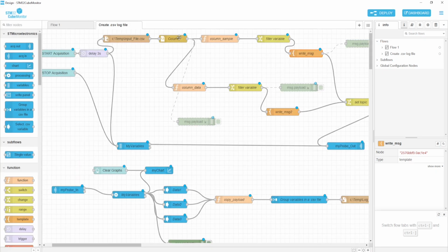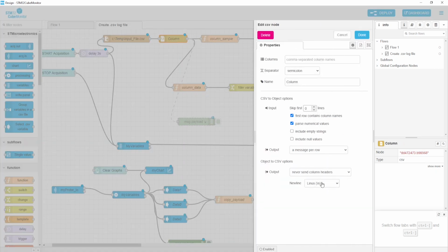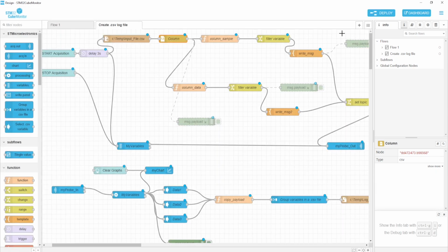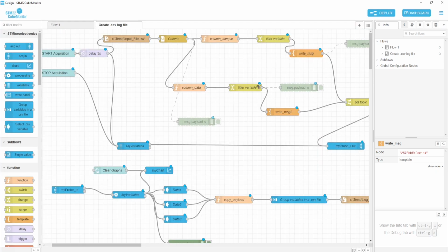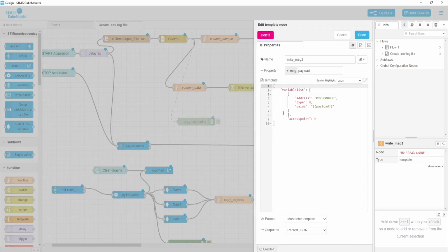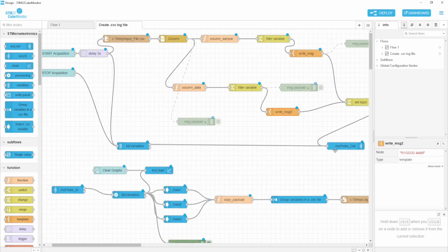So you're gonna catch each line from my CSV file. Each line from my CSV file, I'm gonna take this information and split between the two columns. The first column, I will get its value and save its value in the sample input variable. The second column, I will separate its value, treat its value, and copy its value to the data input variable. After that, I'm gonna connect this by the ST link to the application running the microcontroller. So this is the input process, basically.